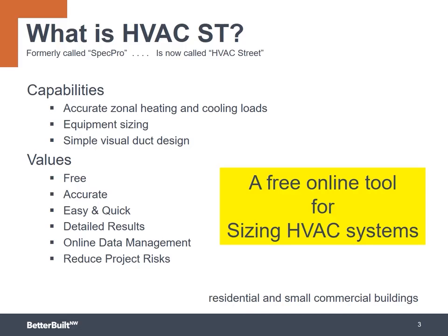And one of the big pluses to me, and we've heard this back from several contractors that started to institute sizing on every job, is it reduced their risk overall. Everybody knows the worst thing as a contractor is to have to go back to a house on your own dime. The right size of equipment, the right size ductwork helps ensure that there's no short cycling, that the right amount of cooled or heated air is delivered to each room. In other words, that you're delivering the comfort that you promised your customers.